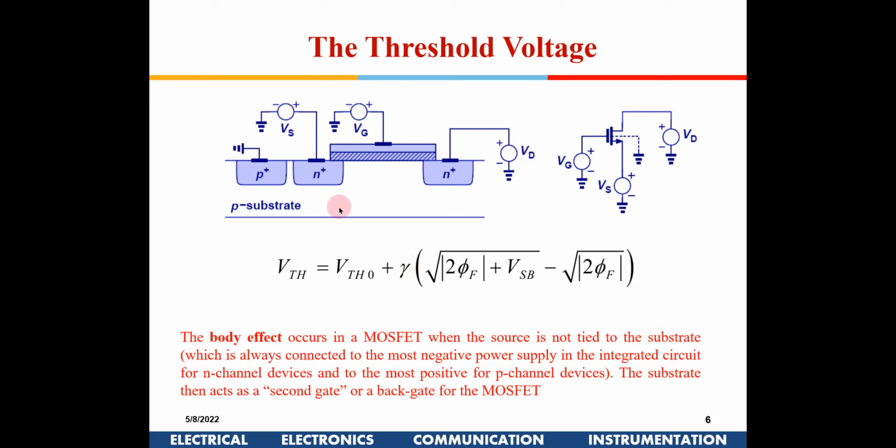So you could relate it like this: whenever a gate potential is applied, an extra voltage is applied out here. Instead of thinking that this is at a positive voltage, we could also look at it this way: this is ground and a negative voltage is applied out here, okay. Now if I consider this MOSFET as a double gate structure, if I am giving a negative voltage out here, then it is opposing the positive voltage which is applied on the front gate, okay.